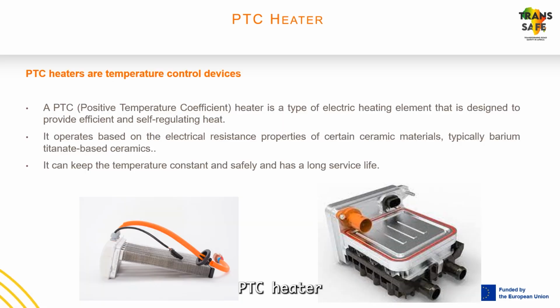PTC heaters are temperature control devices. A PTC heater is a positive temperature coefficient heater, a type of electric heating element that is designed to provide efficient and self-regulating heat. It operates based on the electrical resistance properties of certain ceramic materials, typically barium titanate-based ceramics, and it can keep the temperature constant and safe and has a long service life.